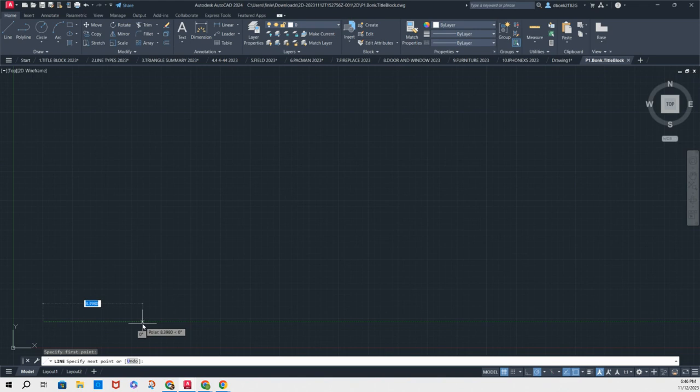All you're going to do is type in the number 11 and then hit enter, and it's going to make the line that 11-inch measurement, and it's going to keep it there at 0 degrees for right now. That's all you need to know. Just hit enter. So all I did is make a horizontal line going to the right, exactly 11 inches long. We're going for a layout that's the size of a piece of regular printer paper, which is 8.5 by 11.